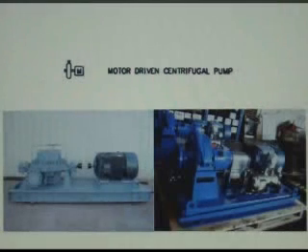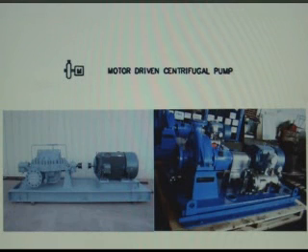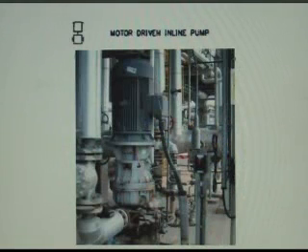So motor-driven centrifugal pumps, or centrifugal pumps, can be driven by a motor or a turbine. You have a motor-driven single-stage pump or a multi-stage pump. This is a motor-driven inline pump. The pump is actually at the bottom of all of this. It's called inline because it actually sits between the 2 flanges on the pipe, just kind of on a little concrete pedestal to take the dead weight.